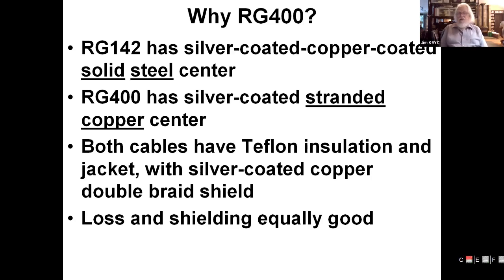The difference is... both cables have Teflon insulation. They both have a silver-coated double braid shield, which makes the shielding very, very good. That's why these cables are very popular in repeater stations and similar installations. And the loss and shielding are equally good.